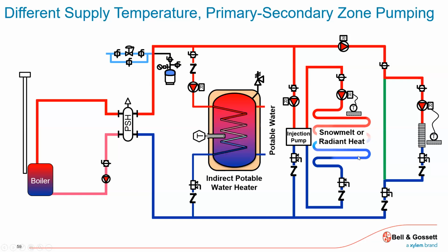You can use that. Here's an example of that low loss header. This guy here that we were talking about earlier. Primary, secondary connections. Here's the example that, yeah, I can use it as an air separator, but I'm also using it as my primary, secondary tees. So I've decoupled the boiler plant from my system. And then from there, I've got, you know, a domestic hot water. So maybe I want straight boiler water to heat the domestic whenever there's a call.